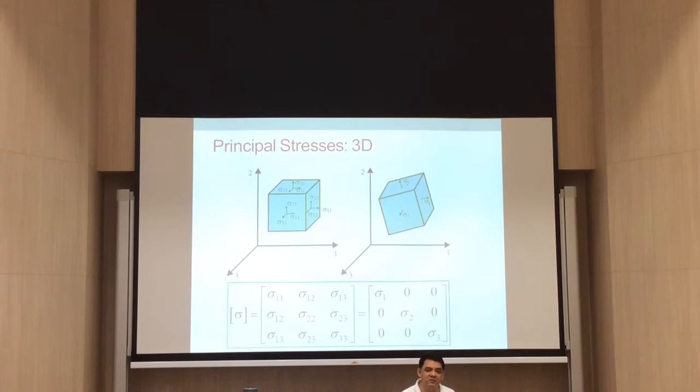That will be the maximum stress occurring in your structure. So if you have solved everything and calculated this sigma 1 in the structure, how do you know that your structure is safe? You compare this with a material property. We call that ultimate strength.